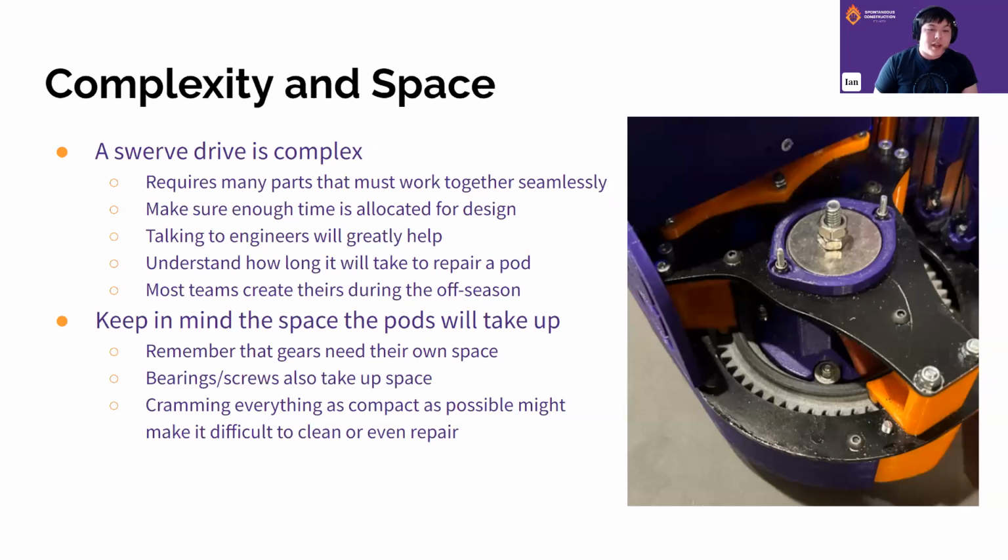It's also important to keep in mind how much space the pods will take up, as all the gears, bearings, and screws will take up their own space. And while cramming everything together as compact as possible might seem like a good idea, in the long run, it can make it a lot more difficult to clean and repair.